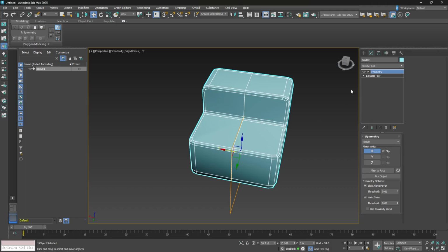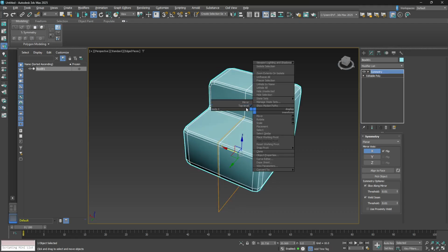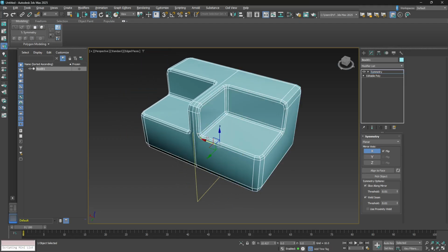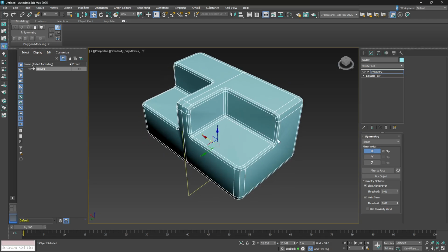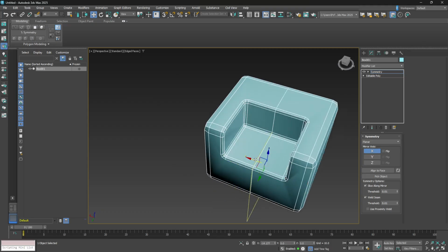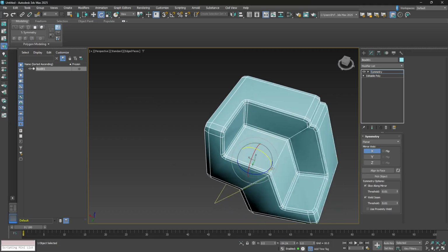And then this is where Blender and Max can do basically the same thing, but Max is already set up with it, which is, once again, drop down. There's a mirror here. This used to be just called the gizmo or whatever. And you can see we can grab there, right click, boom. And now we can just set the offset of the mirror, or the symmetrize anyways, not the mirror. If we want to flip it and go the other way, we can do that. If we want to rotate this thing, we can.